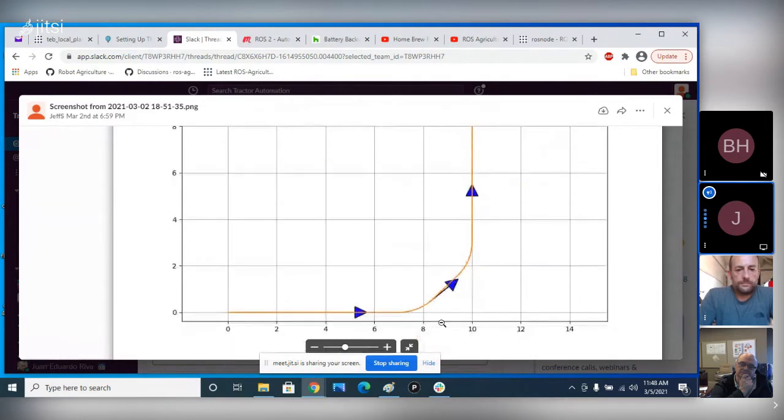So what you have to do is, once you get to this point at 8, you have to pick a point here at the beginning of this line. When you do, it'll create a curve to that and come into it at the angle you want. And from there, when it draws the next line, it'll draw a straight line right on the line that you told it to.